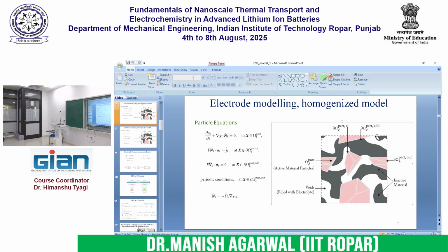Again, the periodic boundary conditions are not used heavily in the homogenization field, whether it is thermal homogenization or structural homogenization or whichever kind of homogenization it is. Okay, fine. These equations are known as particle equations because you are solving now at the particle level. Earlier we didn't need to give them a special name because everything was resolved at the micro scale, but now we are working at a different scale. So here we add the disclaimer that these equations are solved at the particle level, and that's why we are calling them particle equations.